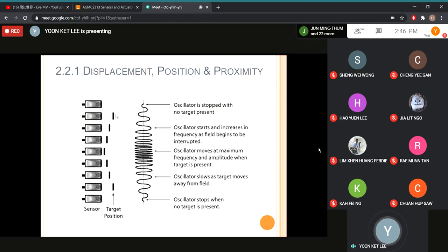That's why when you use a capacitive sensor, you need to justify your detection range to suit the application of your project. Make sure you place your capacitive sensor very close within this range, so that you can detect the object when it passes by.